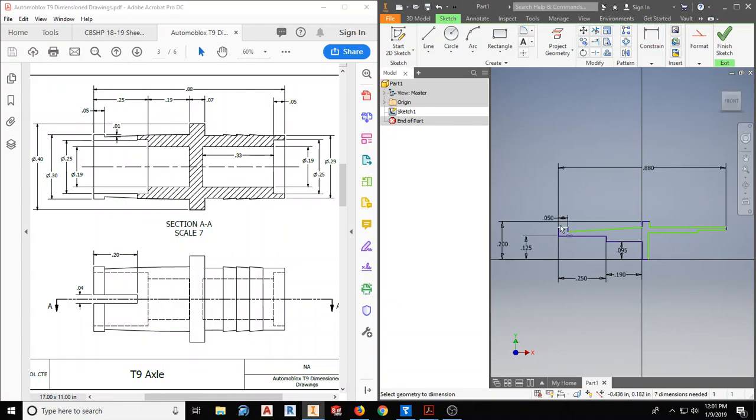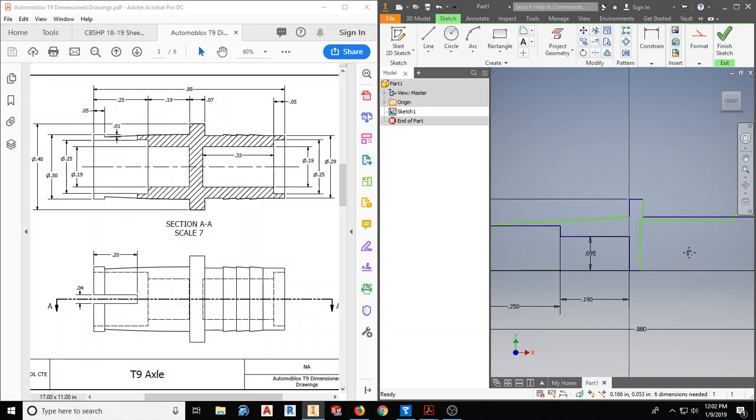I've got this line for the nub and this line right here for the revolve, and that is going to be half of 0.30. So in that case, half of 0.30 is 0.15, or you can type it in as 0.3 divided by 2. Either way is fine. It shifts it down. Now things look a little skewampus. That's okay. Take a look at what I'm going to do here.